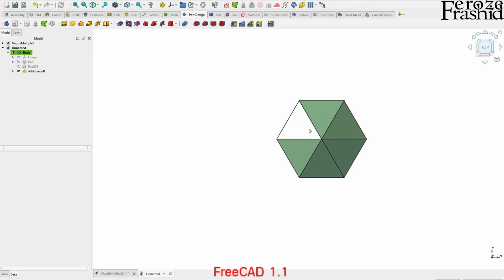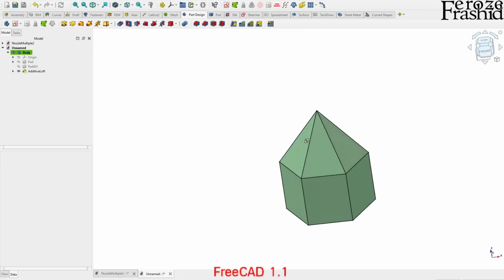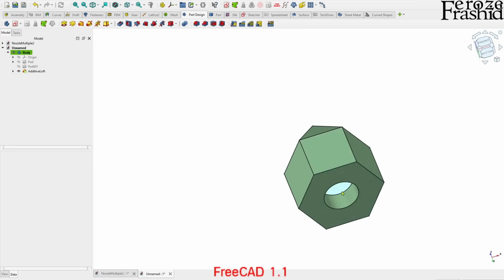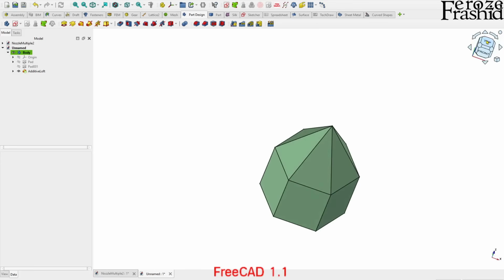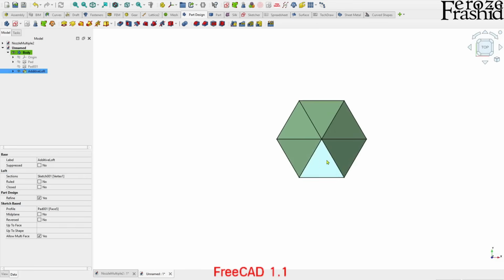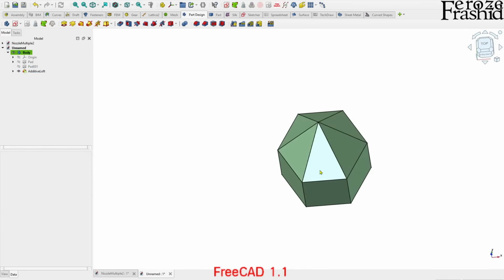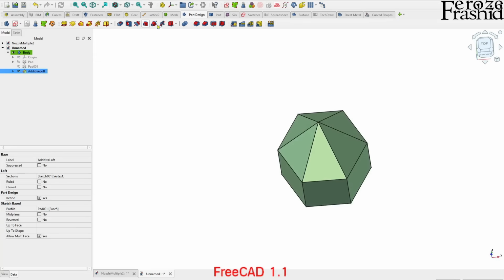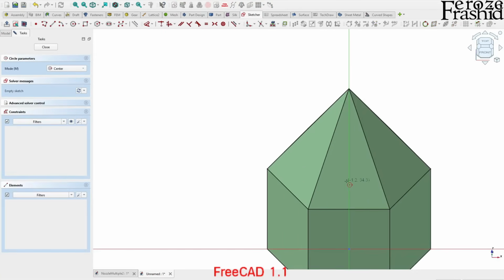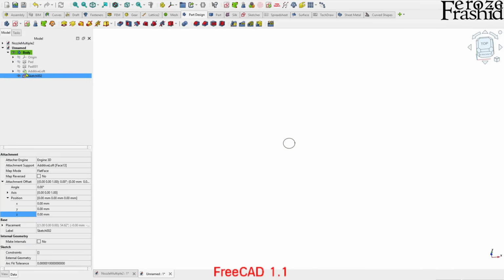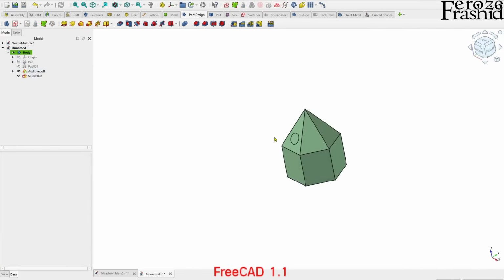And then now we have the 6 faces. On one of the faces I'll have to make a circle to actually relate to this. So looking from the top view, I see that these 2 surfaces are my primary candidate because they actually align with the view. So I'll take this one and draw a sketch directly onto that face, right? And say, let's do a circle. Okay. So we have all our things.